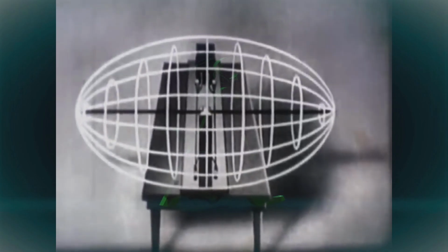This is your basic antenna. It is called the half-wave dipole antenna. Our tabletop antenna system uses a half-wave antenna. Let's examine the kind of radio waves it sends out. The vertical rings represent the magnetic lines. The horizontal rings, the electrostatic lines.